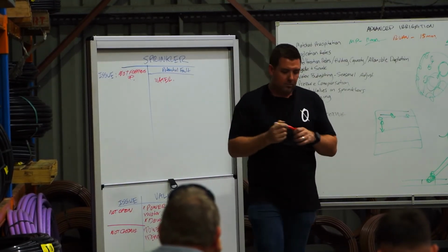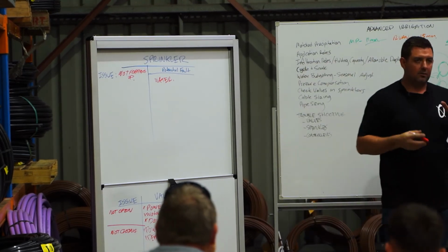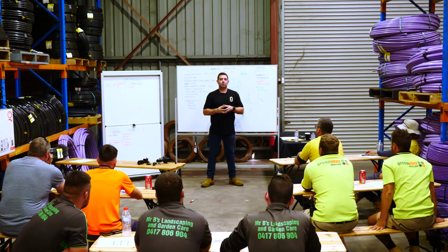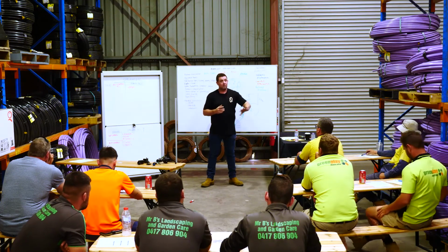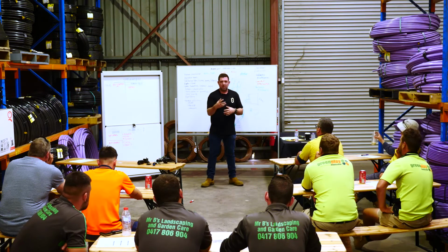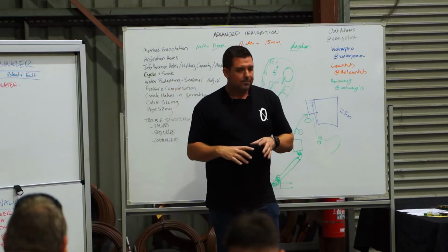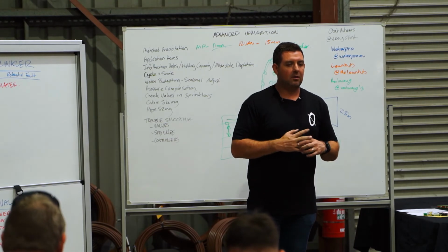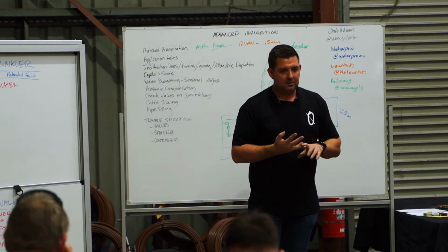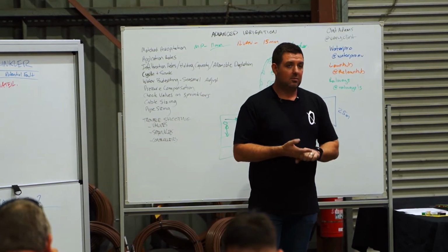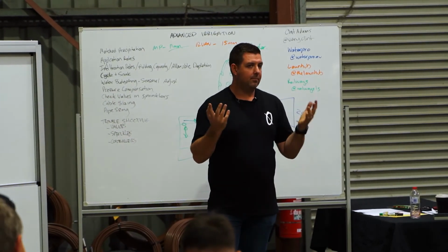job recently through Facebook. We're part of a lot of online communities, and we get a lot of irrigation designs come through our website, and then we do the design and we send them the quote, and then they buy the stuff, we send them the stuff. We had a system where the guy's flow test came back at 30 litres a minute. His system was designed at 18. We sent him the system, he put it in and it wouldn't pop up.